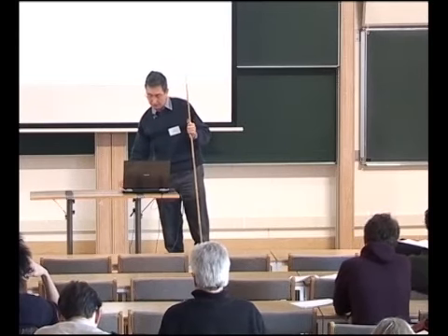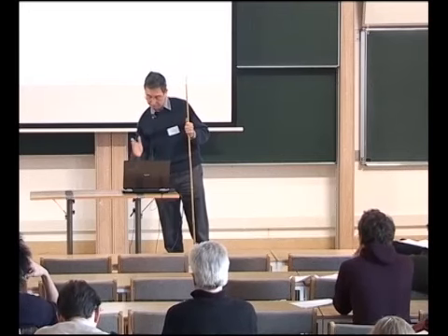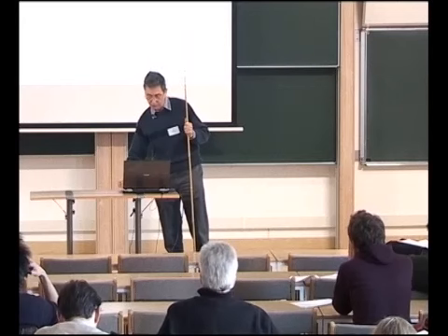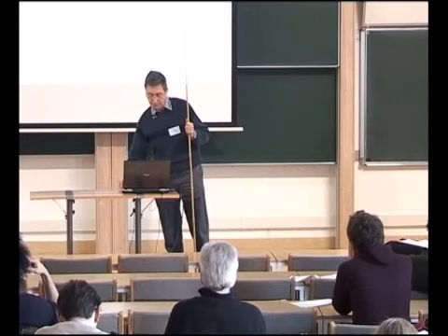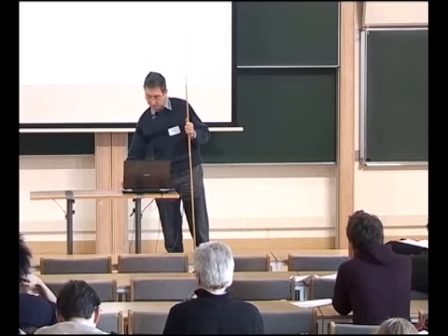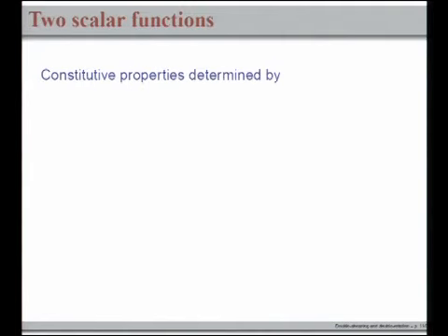Even though it's not necessary for the model that I'm going to consider, I will take the OX3 to be a principal stress direction, because to assume otherwise gives rise to rather peculiar problems, and so I think it likely that the OX3 will be a principal stress direction. I'm certainly going to assume that today, but it's not necessary. Now, the constitutive properties of these rate-independent materials are, in the model I'm going to present today, determined by the usual plastic potential function and yield condition.